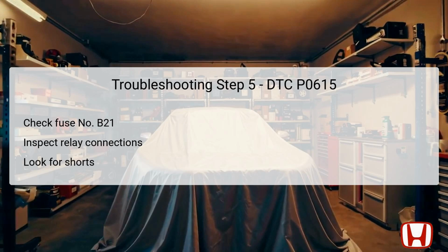Inspecting this fuse is critical, as a blown fuse can interrupt the electrical flow necessary for the starter relay to function. If the fuse is found to be defective, it may also signal a short circuit existing in the IG1 ACG wire, which needs further investigation. Should the fuse be intact, proceed with additional testing to resolve any underlying issues affecting the starter cut relay circuit.